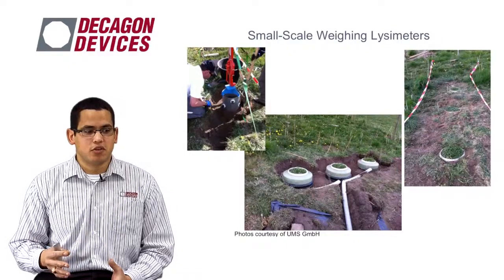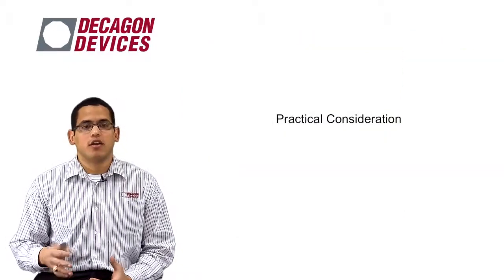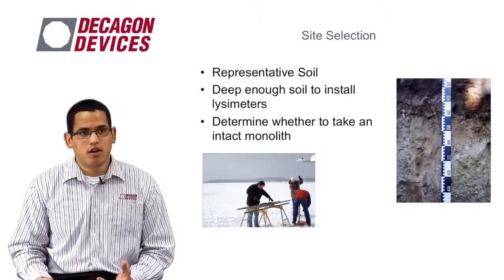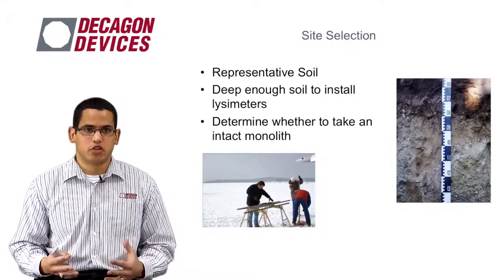So now we'll move into some practical considerations. There are many considerations that you need to think about when you're wanting to install lysimeters and trying to take these measurements. One, it's important that you get representative soil of what you're trying to measure.